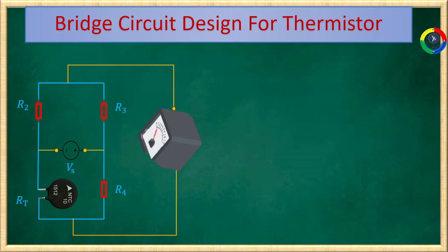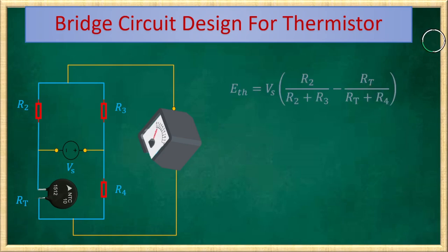R2, R3, and R4 are purely resistive, and our sensor is also resistive, RT. Therefore, by replacing all the Z's by their corresponding resistance, we can write our previous ETH by this expression, and the equivalent impedance is also replaced by RTH, and this is its expression. Now R1 is our sensor, replaced by RT.